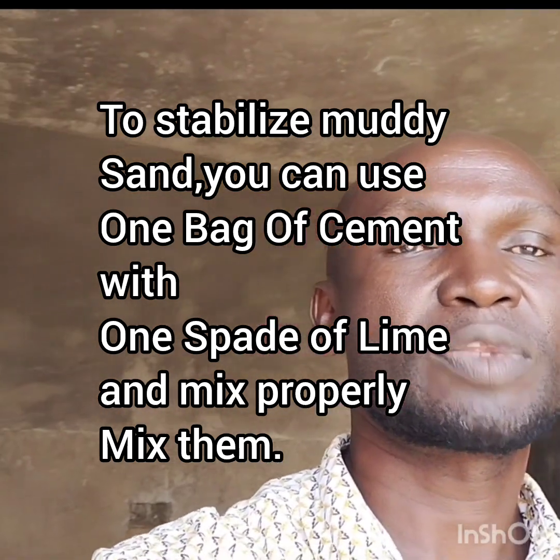That lime will help you in stabilizing the sand, in that the lime is going to bond, or rather mix, with the ions in the mud. So when you do that, you'll have improved that sand for your use.